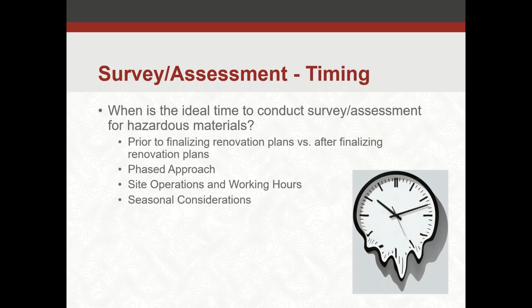Timing's another critical item in your survey assessment. When's the ideal time to do a survey assessment? There's a fine balance between doing an assessment early enough to get information back in time to correlate with your design deadlines, and not going too early, where you don't have enough information to do an adequate survey. So maybe the design has not progressed to a point where it identifies everything that's going to be touched during the project. In that scenario, you might just do a survey of the complete building and say, okay, we'll figure it out later. At least we'll have all the data or information.